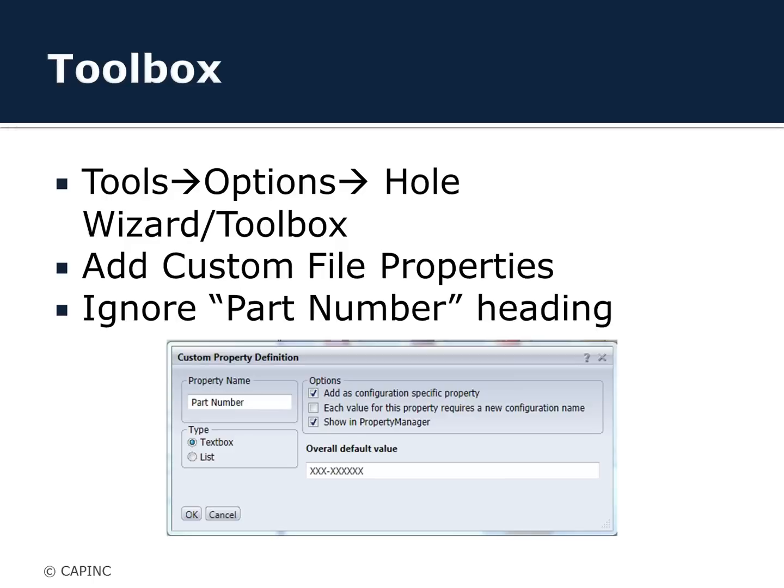and they will pull the same information out of a part file or a toolbox file. Now, Toolbox has their own way of doing things, but unfortunately to use what they call part number in their description, you can't set up the custom properties the way I just showed you in the part template. Like I said in that third slide I think I showed you, there's more than one way to set up templates. So we're not going to go in the way that the Toolbox has already defaulted. We're going to show you a new way of doing it. Like I said, it's not the only way, but it is the way we recommend.